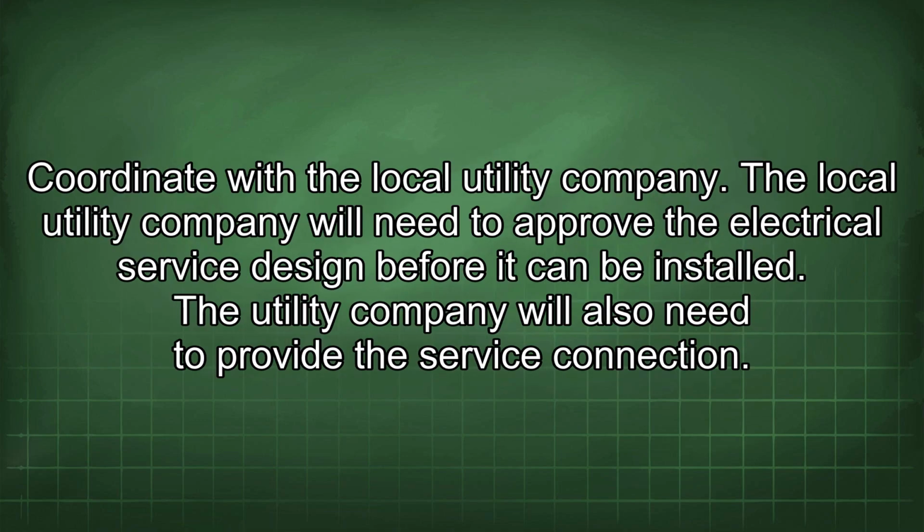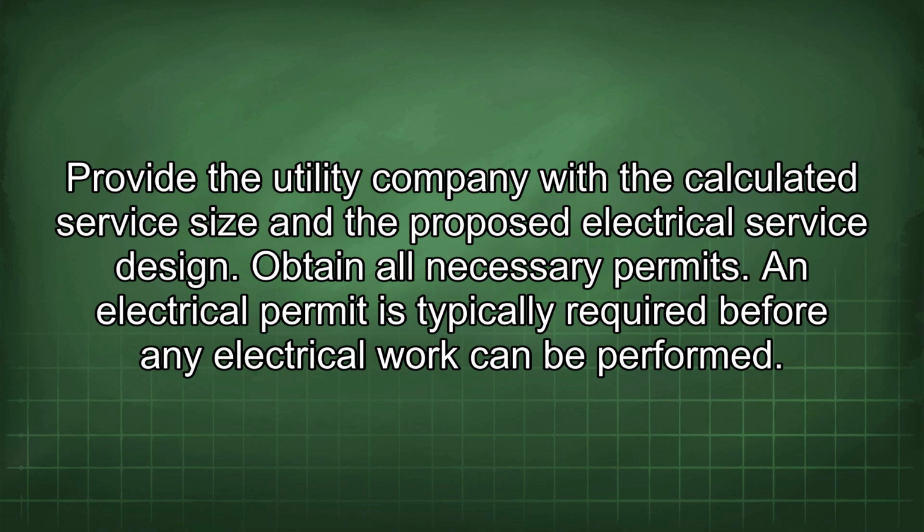Coordinate with the local utility company. The local utility company will need to approve the electrical service design before it can be installed. The utility company will also need to provide the service connection. Provide the utility company with the calculated service size and the proposed electrical service design.